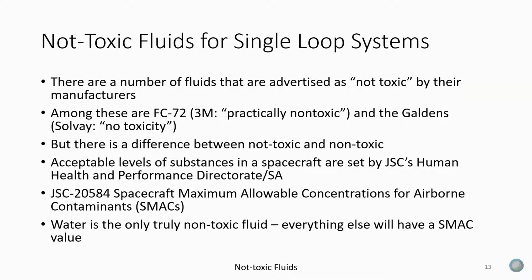So we're talking about non-toxic fluids. We've got things like FC72, and 3M, who's the manufacturer, says it's practically non-toxic. I love that because it's practically. So what does that really mean? And then we've got the Galdens, and Solvay, their manufacturer, says there's no toxicity in their literature. But as I said before, there's a difference between not toxic and non-toxic.